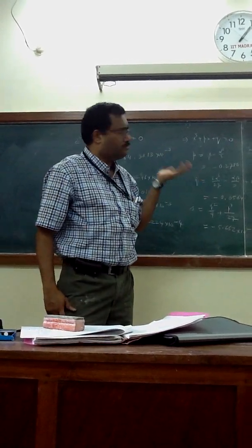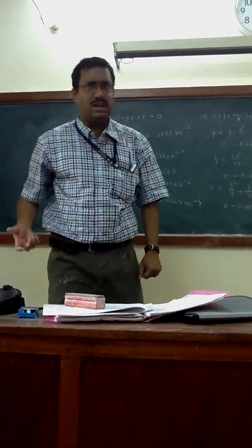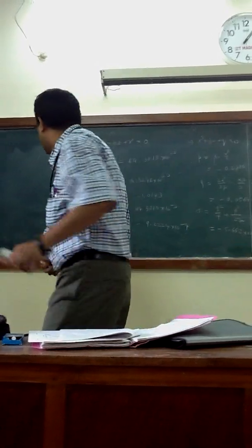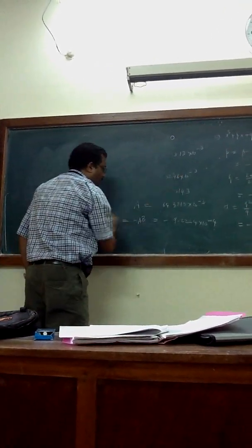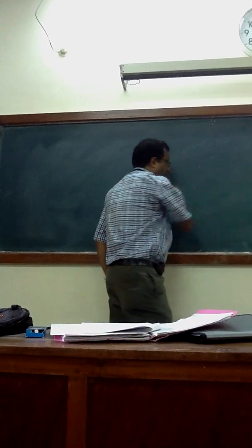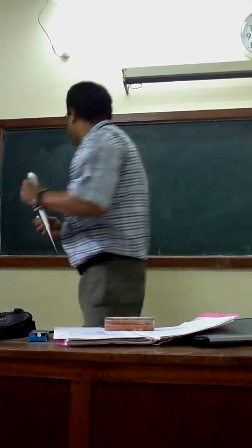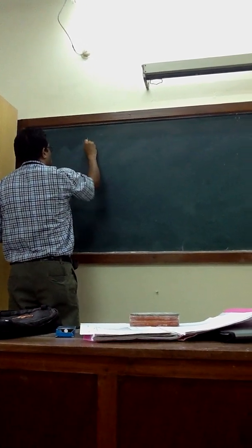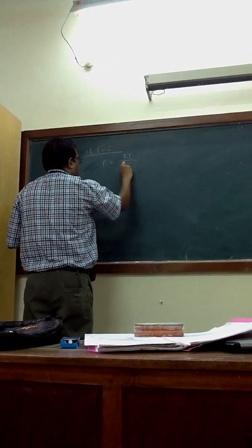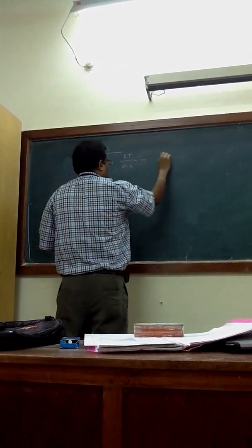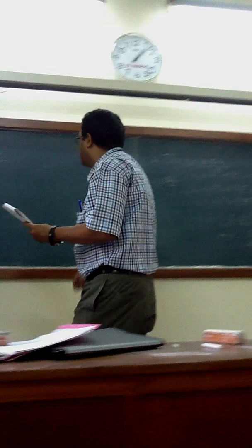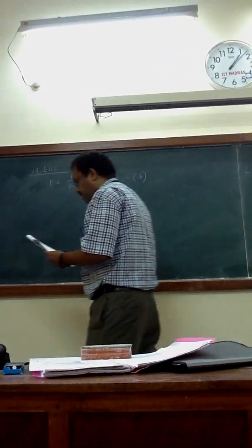Generally people measure these experimentally, but you can calculate a and b mathematically for an equation of state. So let's look at that part and calculate a and b and show it for van der Waals. You can go back home and try it for SRK and Peng-Robinson equations of state. So let's look at the van der Waals, which is P equals RT by (v minus b) minus a by v². Simplest form. I will call this my equation number 1.